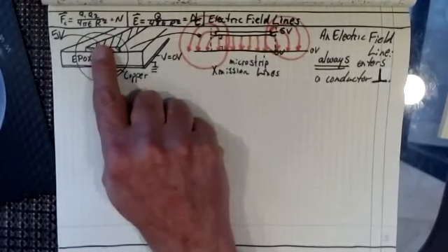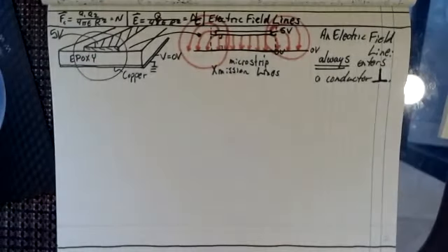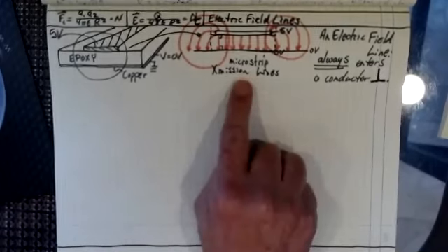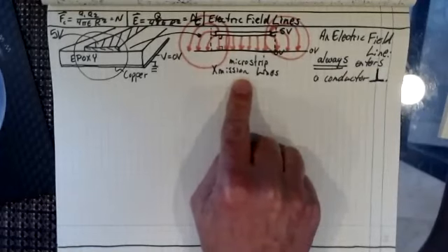You have to match the impedance of this with the impedance of all of the other communication devices within the printed circuit board on your phone. Don't think that your phone does not have coaxial cables. It does. They're just called microstrip transmission lines on the printed circuit board inside your phone.